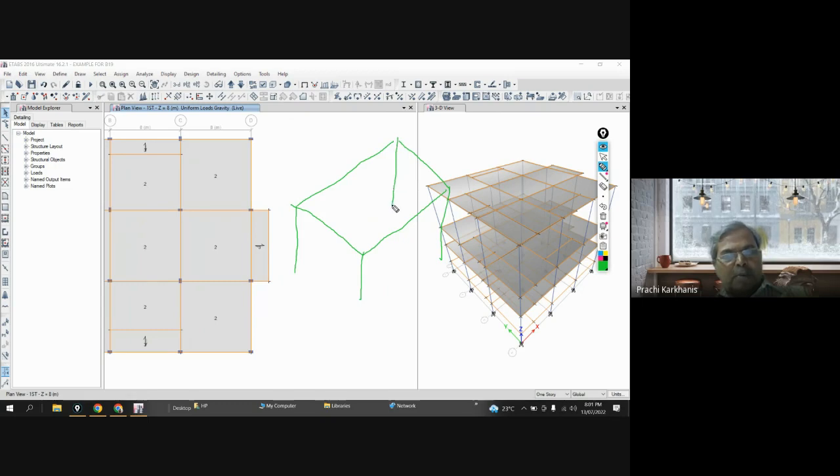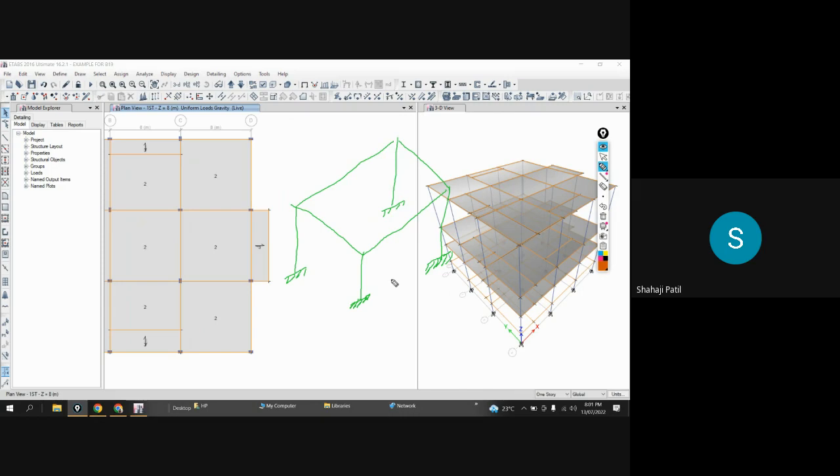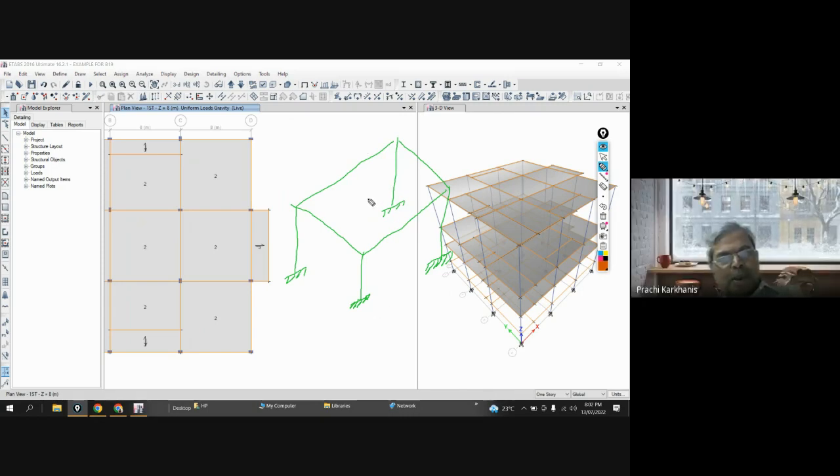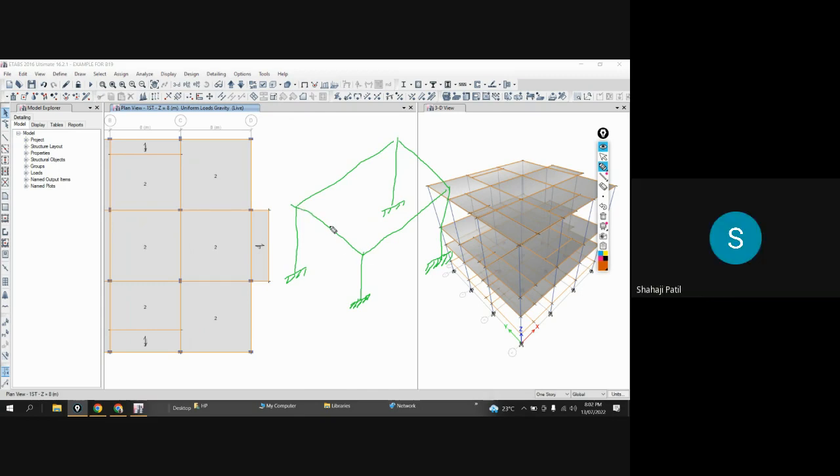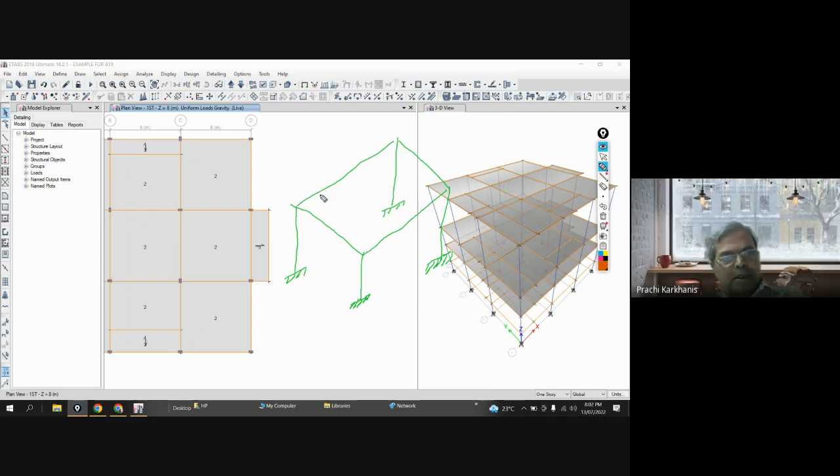Where is that point load coming from? Let me decide that. Yes, anybody? Yes, where will it come from, first we have to find that. Hello, floating column. A floating column is not supported on a slab, the whole slab will fall. It is supported from the beam. See, this is the boundary, and this slab is transferring its loading onto the supports, onto the beams. Once the load is transferred effectively from the slab to the beam, I will say the duty of the slab is over.